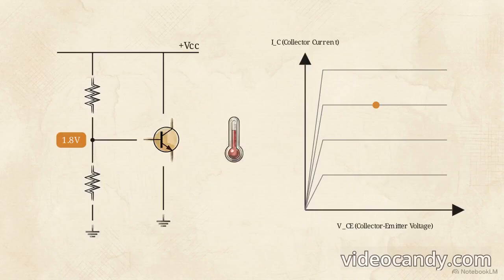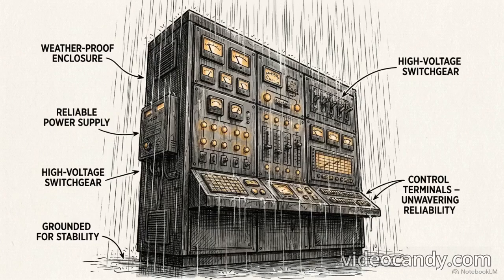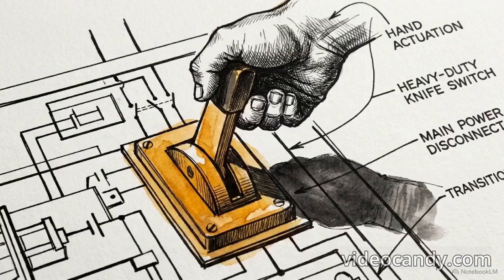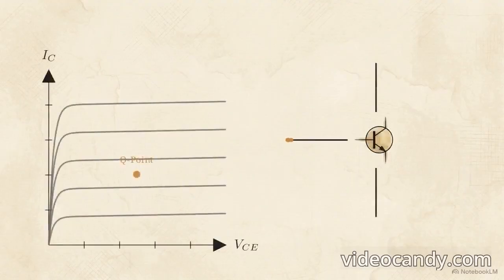To solve this drift, the standard engineering approach is voltage divider biasing. Instead of a single resistor, two resistors form a potential divider across the supply line, feeding the base terminal from the center node. This resistor divider clamps the base voltage to a specific ratio of the supply voltage. By making this node's voltage dependent on external resistors rather than internal current, the Q point remains stable, even if the transistor's inherent beta fluctuates due to temperature or manufacturing variance. Robust circuit design is about forcing the system to remain stable, despite the inevitable imperfections in hardware and operating environments.